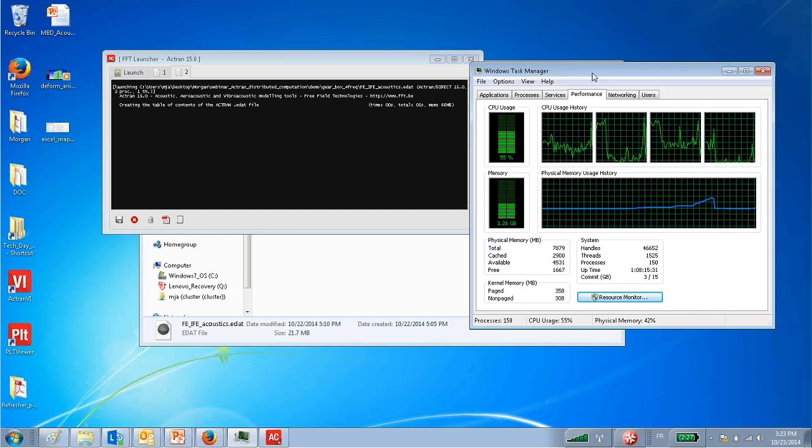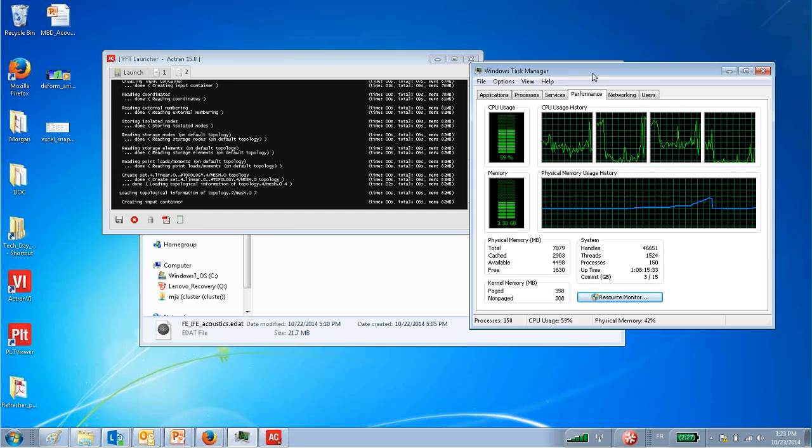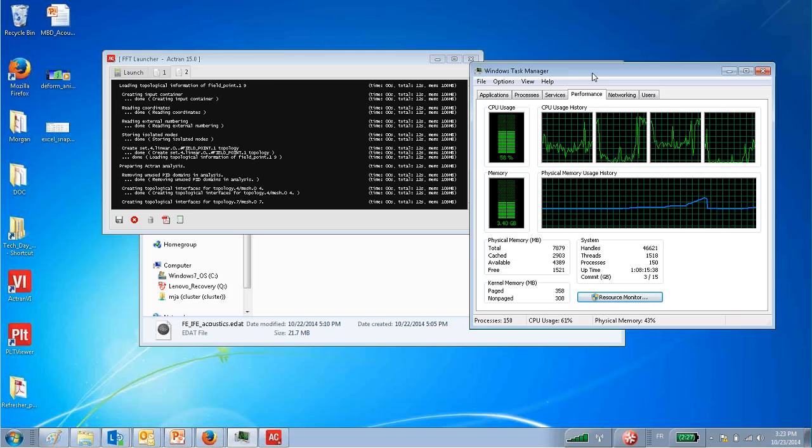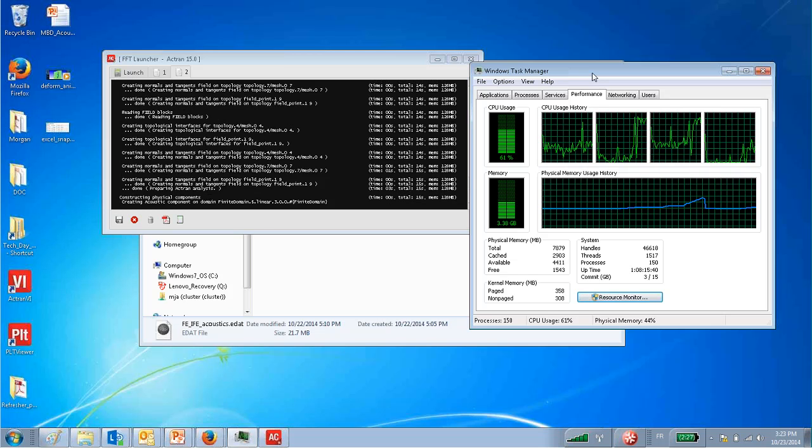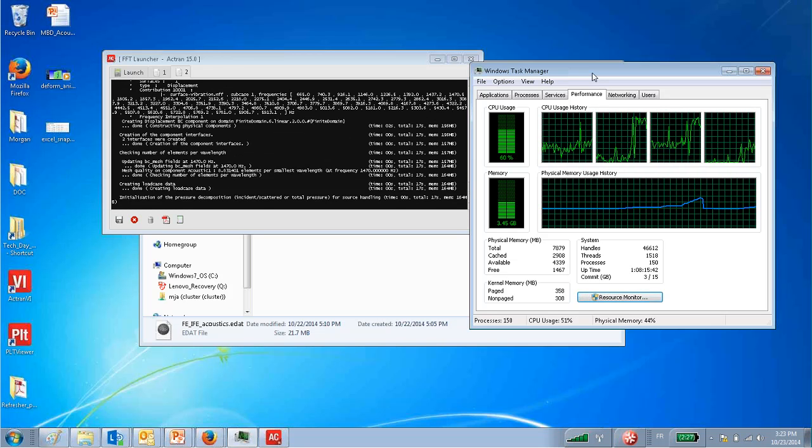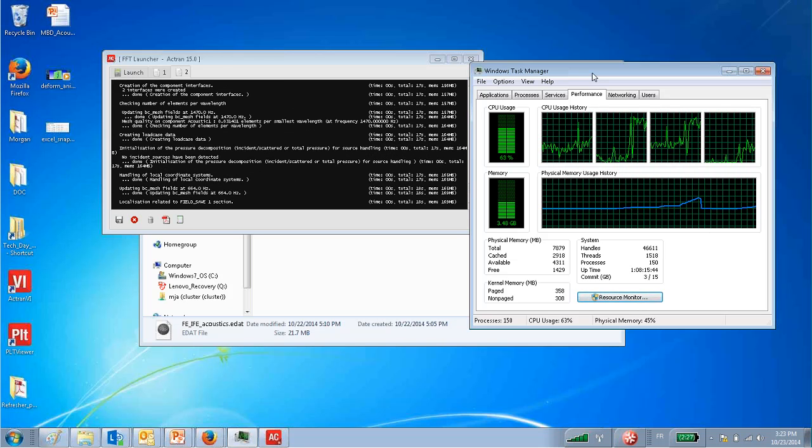If you look at the CPU usage, you will see that we have a much higher number right from the beginning of the computation until the end, because there are 2 processes that are using 2 different cores to run the computation. I think that you have like 6 frequencies to solve. Yes, right. Then it means that we have 3 frequencies on each process that are going to be solved. Okay, so the expected computation time is about half of the sequential computation time.